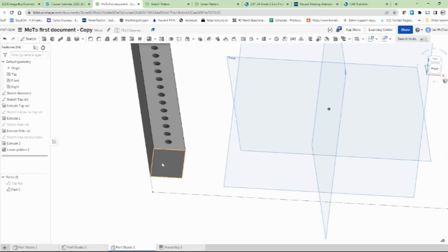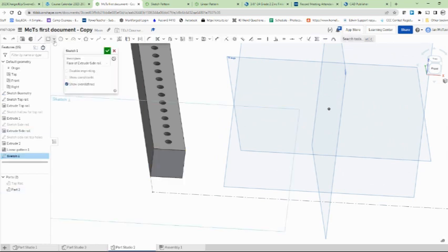So the last step, I'm just going to create a sketch, and this is what we did the other day. We used a construction line to go from point to point, geometry, and then we did a center point rectangle. And whoops, I'm going to undo that. The reason I'm going to undo it is I'm going to make sure I don't have the construction tool selected. And dimension, I want that to be 1/8 of an inch. That to be 1/8 of an inch.